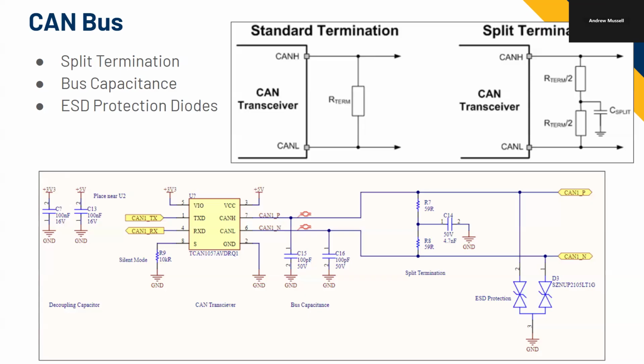So when you have a really high current transient hitting that really high impedance, back to first order principles, voltage is equal to current times resistance. High current, high resistance, I'm going to get a high voltage, and that will get clamped by the ESD protection. You also have the capacitors here, which will get charged really high, and you'll get a high voltage that will trip the ESD.